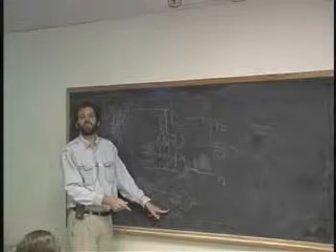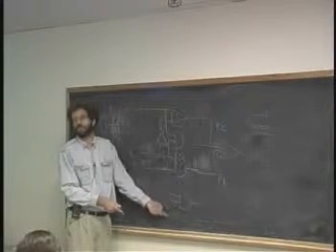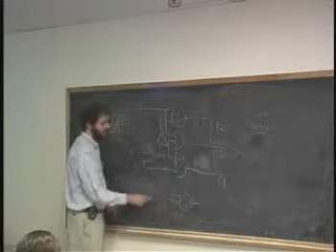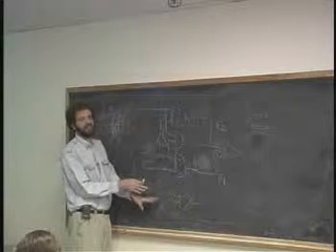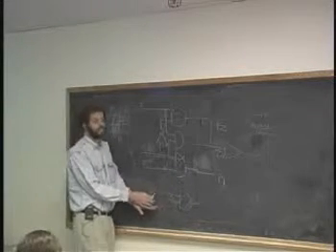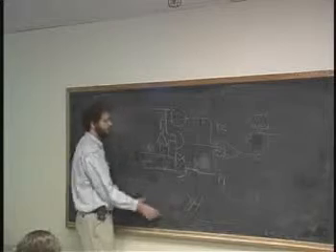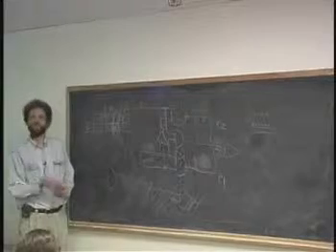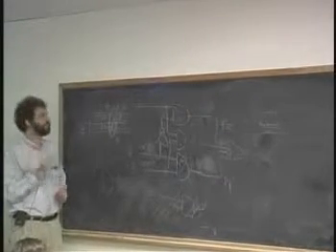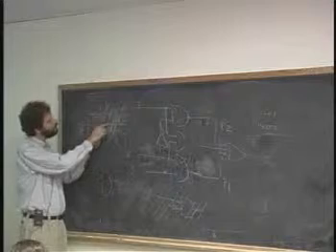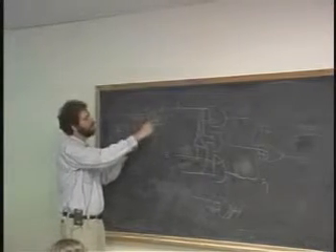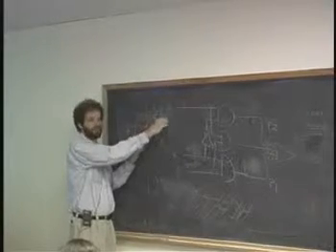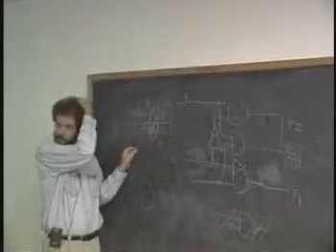However, would you ever want to do this? Does it ever make sense to put A and A bar? No. So this might generate a glitch. Technically, it is sum of products, but there'd never be a reason to do it. So for any practical sum of products logic circuit, you can never get a 0 to 0 hazard, again, for a single input change. And if you cover the path with AND terms so that there's never an interruption of these circles as you transit around, you can never get a 1-to-1 hazard.